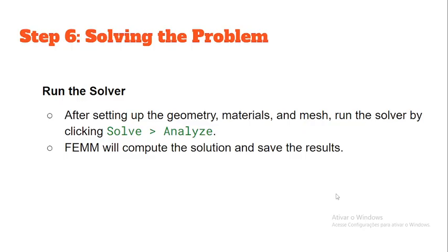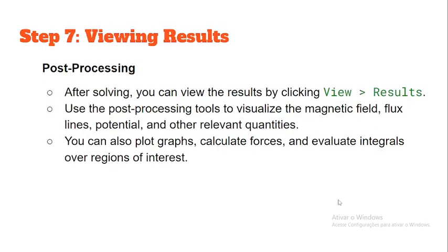Step 6. Solving the problem. Run the solver. After setting up the geometry, materials, and mesh, run the solver by clicking Solve, Analyze. FEMM will compute the solution and save the results.